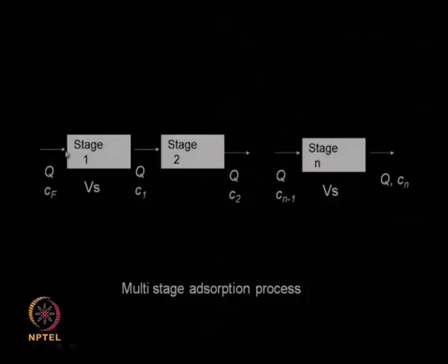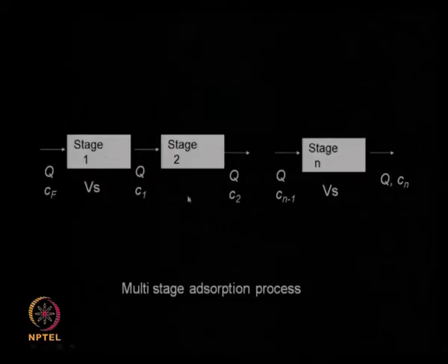So there is a solvent flow and a solute flowing inside at a concentration Cf, then again there is a solvent flow out, there is a solute flowing out at a concentration C1, but inside things are well mixed, we can consider it as a stirred tank vessel, and then this material is flowing into the second stage.